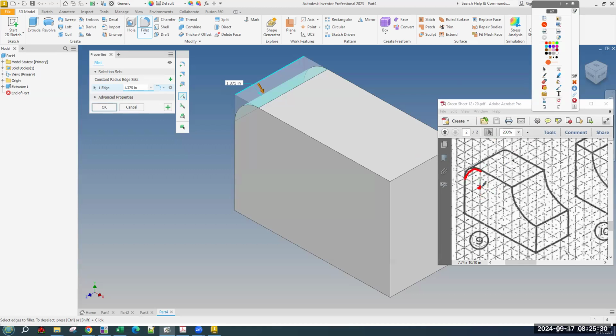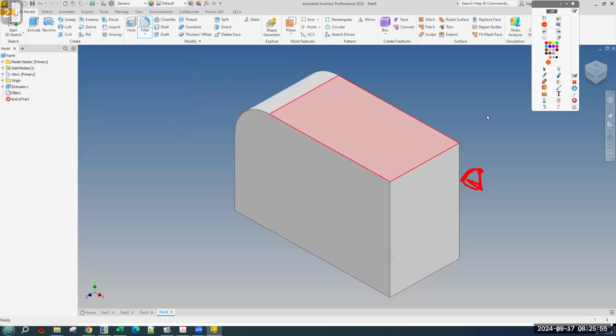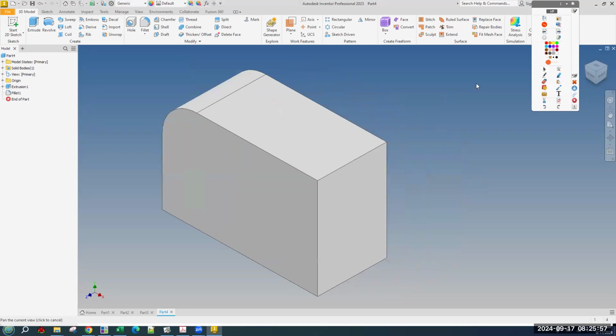This isn't part of the part feature. It's just a little hint there to let you know that the radius of this arc is 2. It is a 2-inch radius, which obviously it's not a complete circle, which would look like that. It's not a complete circle, it's just rounded over. And the distance from the center point in both directions is 2. And that's what we're going to type in here, 2. And there's your baby's first fillet.